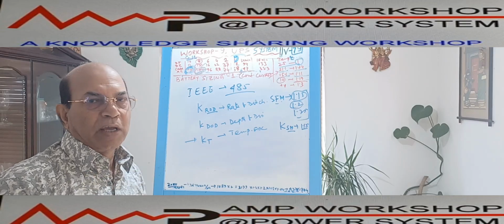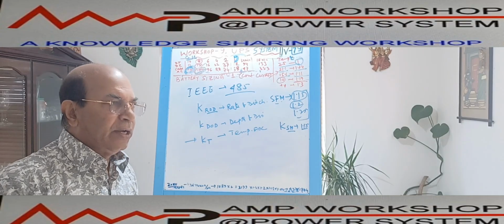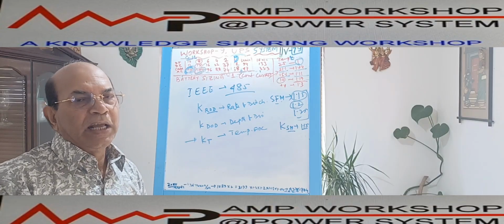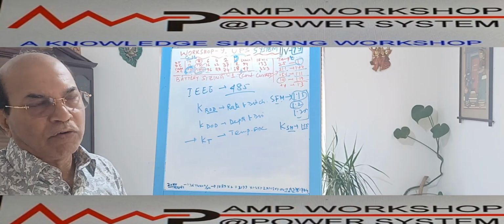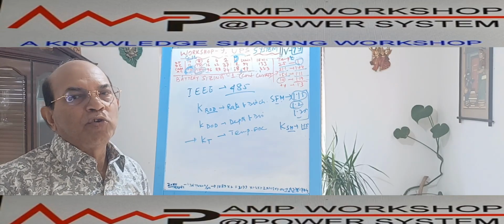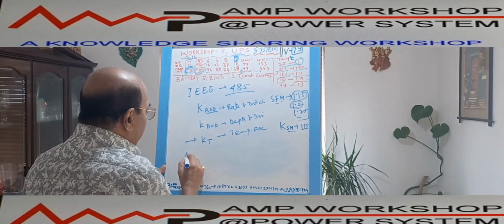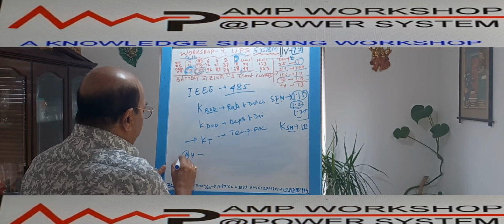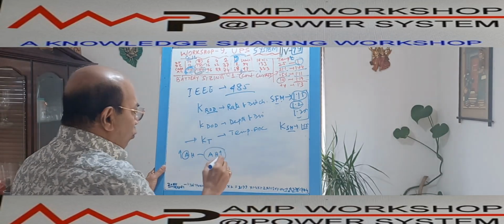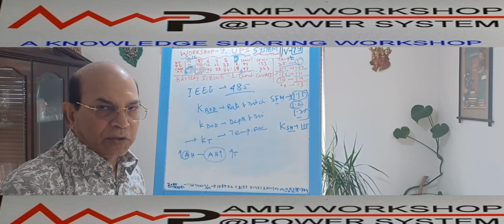Now, all the electrochemical reactions depend on the ambient temperature, the temperature at which the reaction takes place. If you increase the temperature, the electrochemical reaction automatically goes faster, or takes place more vigorously, and if the chemical reaction takes place more vigorously, it will produce more current. If the current increases, the ampere hour also increases, so it will give more ampere hour. So as the temperature goes up, each battery will give more ampere hour capacity.